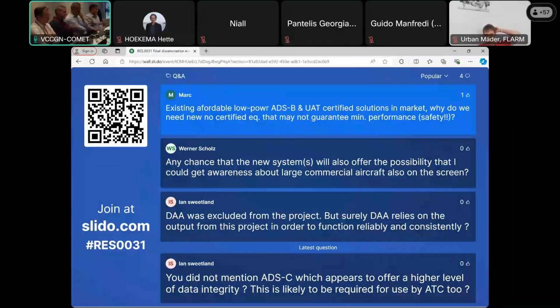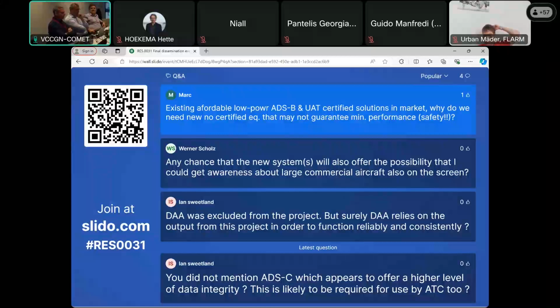I guess maybe you can complement. Yeah, definitely. You've answered most of the question. Just to make sure, low power ADS-B or UAT transmissions are not allowed in all of Europe. First of all, low power 1090 is not allowed in Europe because it would require filing a difference to ICAO's international standard, and that would entail agreement of the 27 plus additional EASA member states to support it unanimously, plus that's the aviation part, but also telecommunication regulators to support it. So that's a serious endeavor, but we will be looking at that as well.